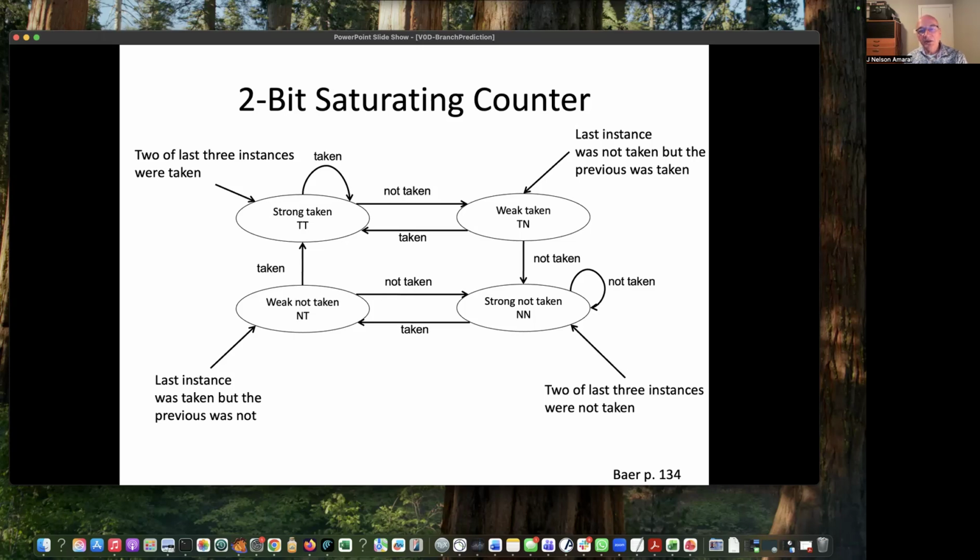So this is how I implement the hysteresis cycle in a branch predictor. Instead of storing only the last outcome of the branch, I have 2 bits that can track the recent history of this branch. Note that if I start with the branch being strong taken, top left of the slide, it will take 2 not taken branches before I change my prediction to the not taken state.